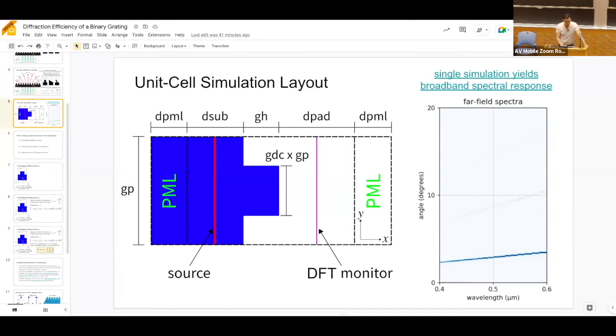So we first check that if we have a normally incident source, we use a mirror symmetry plane in the y direction. And if we are coming at an off-normal incidence, we don't have any symmetry. So unfortunately, we cannot exploit that, so this is just left empty. K describes the Bloch periodic or periodic boundary conditions.